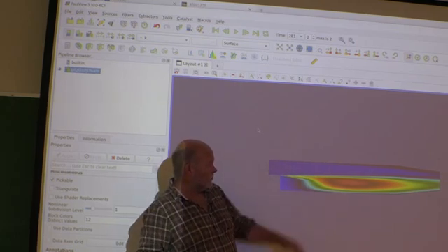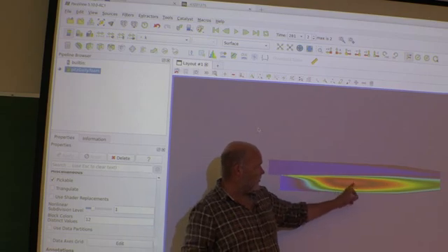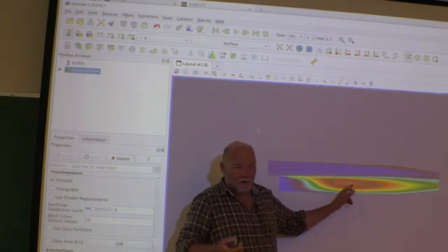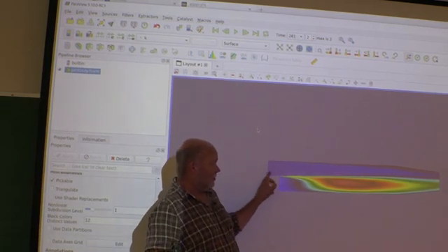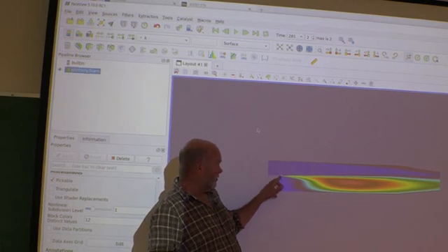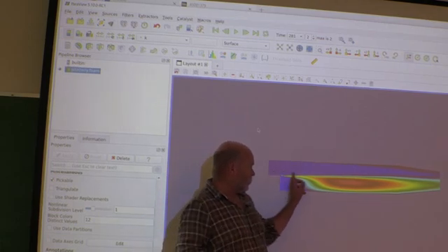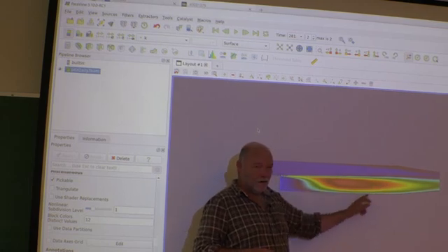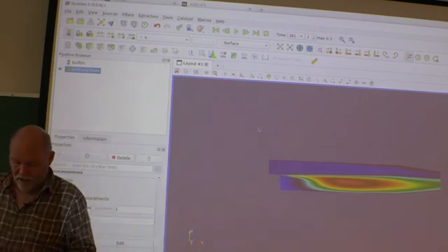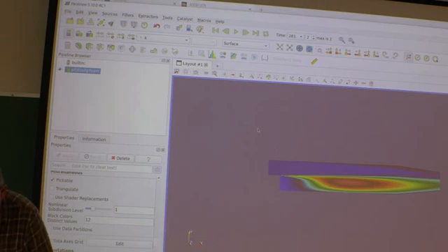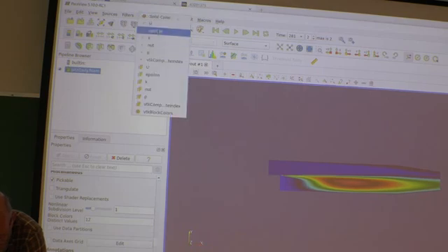Not that they necessarily say so much. Why is K biggest here? Well, why not? I mean, you produce the turbulence typically alongside the walls, especially around this step here, and then it's transported and caught inside this vortex. So yeah, it should make sense. But have a look at the inlet values, that they don't overshadow the entire domain, or that they are not totally crazy.